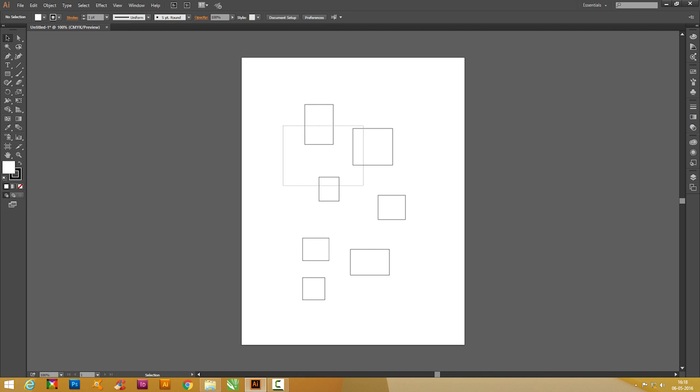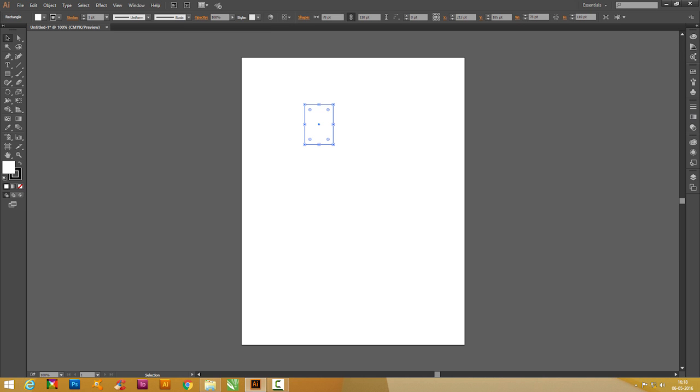Okay, fine. So now after selecting an object, what is that I can do? The first thing is I can move the object. To move the object, I have to click on the selected object, drag it to another location and release. So now the object will get moved to a new location. And now next, while I'm moving, if I'm going to hold shift, then my movement of object gets restricted to 0 degrees, 45 degrees and 90 degrees.